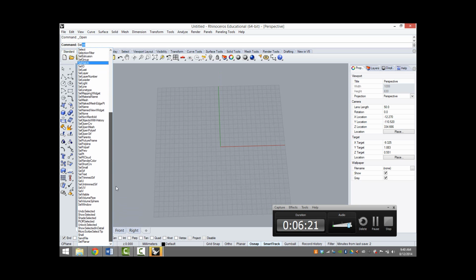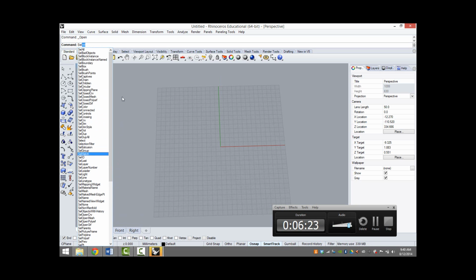This list is endless. So when you start a crazy file that has a bunch of different components and you just want to select all of the points in the file, or you just want to select all of the curves. In Rhino, lines are referred to as curves. And then the abbreviation for that is CRV, okay? You can just type in SEL and you can select your closed curves, or you can select all of your curves, or you can select a particular color.